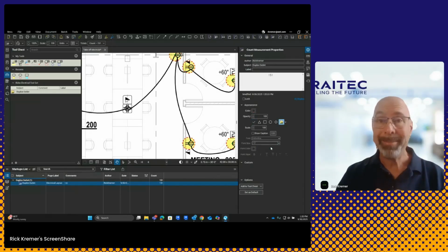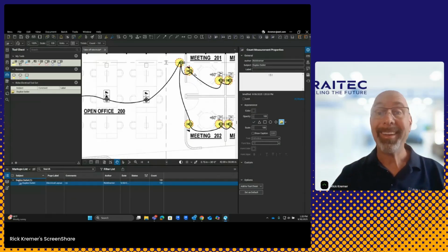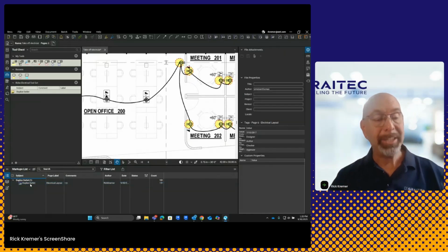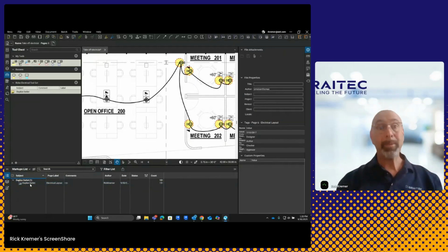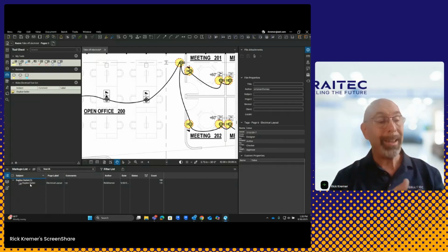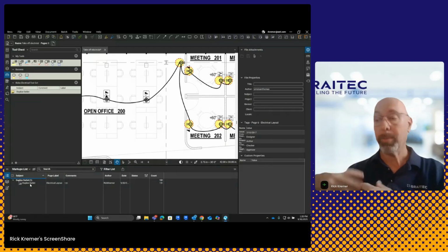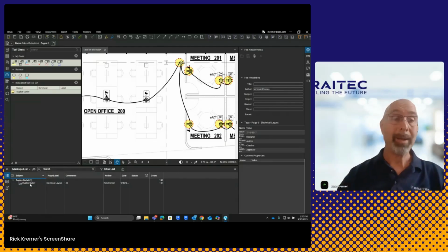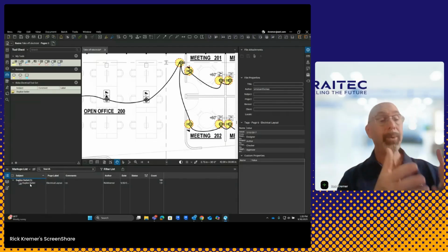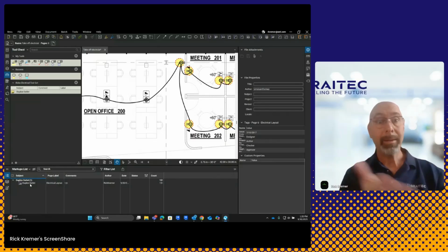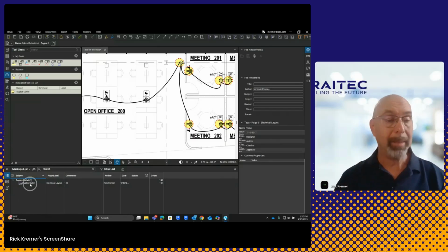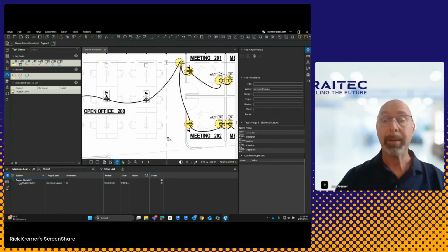Did you see what just happened? It automatically changed it from a generic and changed its name. In Bluebeam Review, it's critical that you change the subject name to what it is that you're actually doing, whether you're marking up a red line, counting an object, whatever it is. I always orient the markup associated with the thing by customizing the name in the subject. Great. So now we have 151 of these objects.